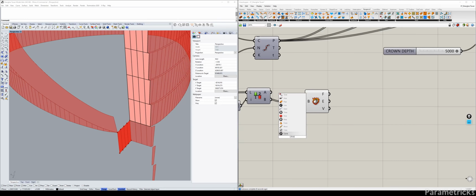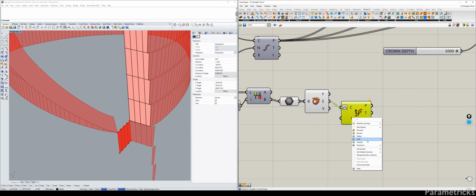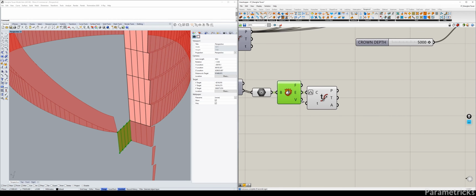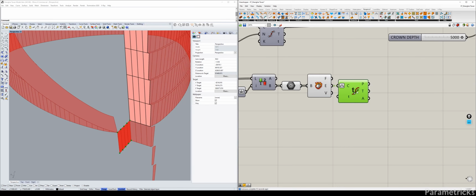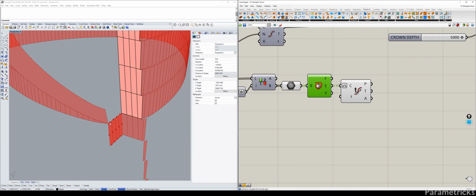So we're just going to quickly do a very rough sorting process. So we're going to evaluate this curve in here. We parameterize it, select the middle point or any other point. We don't really mind, but the middle point will be the best one as long as it's not the first and as long as it's not 0, the end points. Because the logic what we're going to do is we selected, what did I set? Oh, 0.5. Yeah. The logic behind this is the point with the highest z value is where the curve should be where we want to select.